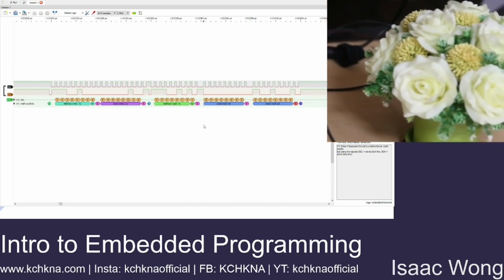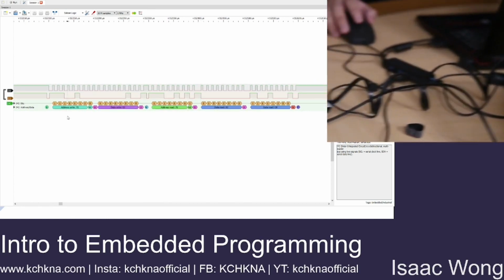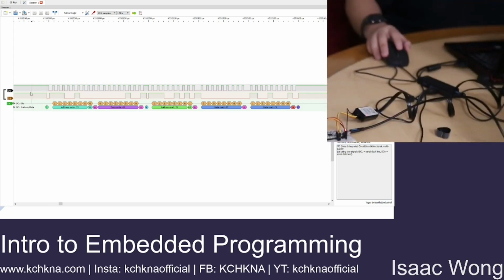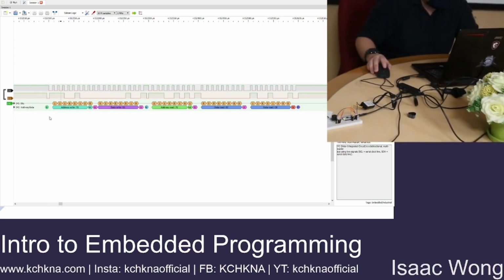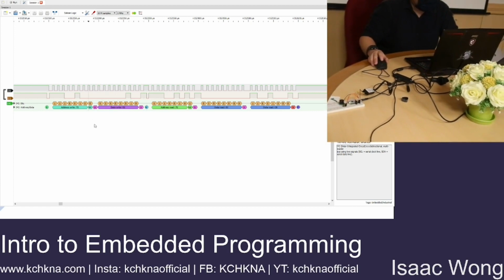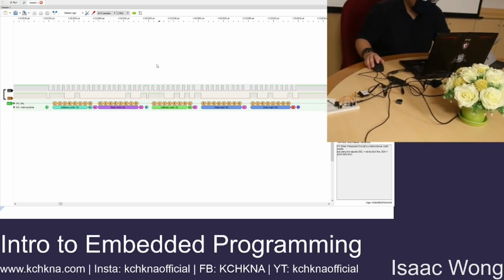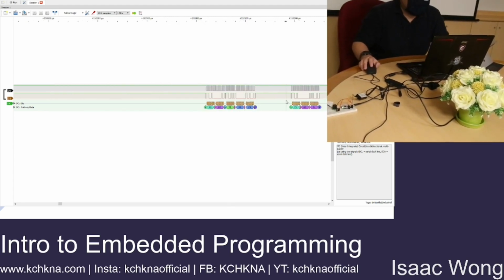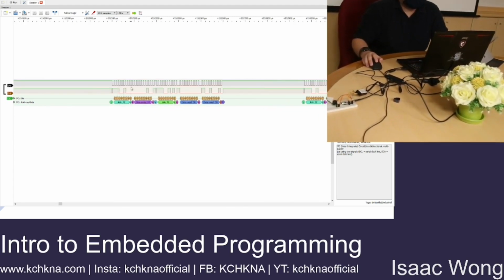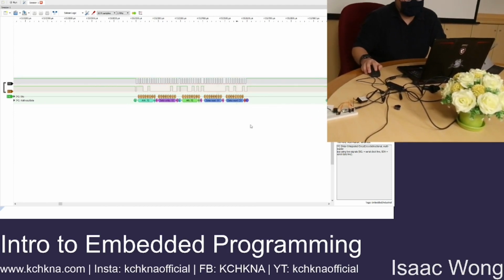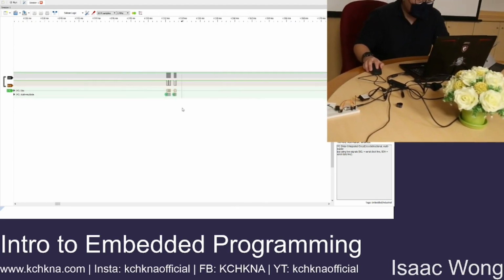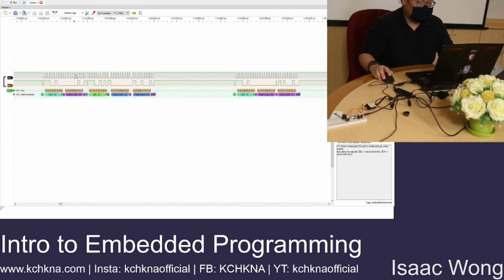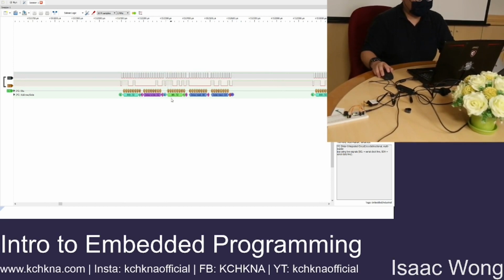And then here we can look very specifically at what is being sent by my microcontroller. So you can see that firstly it addresses the device, then it writes 02, and it executes a read. Now this is actually a separate topic on I2C communication, so we won't be going through this as well. So these are the tools that are actually used for debugging.